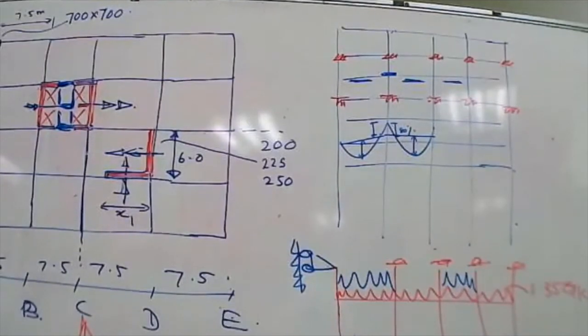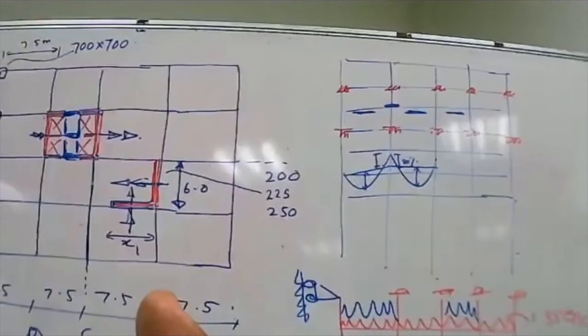So to have satisfactory behavior with respect to the plastic hinge, what is important is the confinement provided by the links, not the longitudinal reinforcement. So by reducing the longitudinal reinforcement at the support, you are not going to reduce the earthquake resistance. Earthquake resistance comes from the confinement that you have provided at the support.